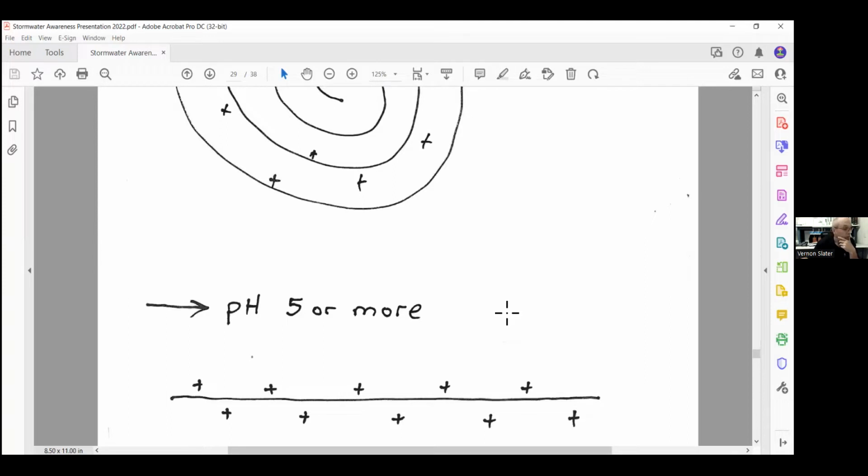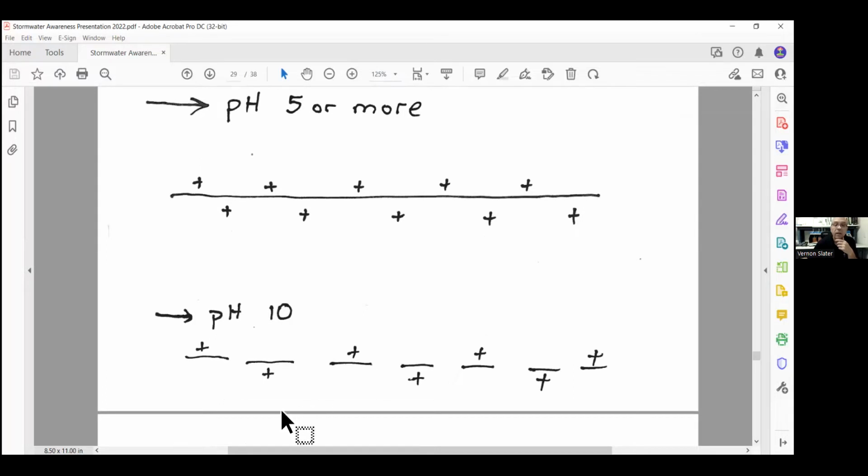Chitosan is pH sensitive and therefore needs to be used in a pH range that is conducive to construction stormwater discharge requirements. When pH is 9 or above, chitosan will not work, as well as at 8.5. At a pH of 10, the molecule becomes severed, and complete flocculation is not accomplished.